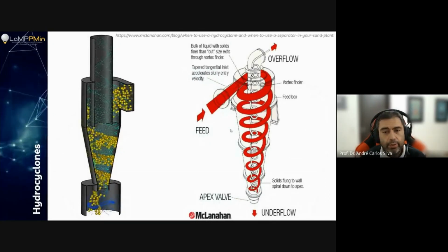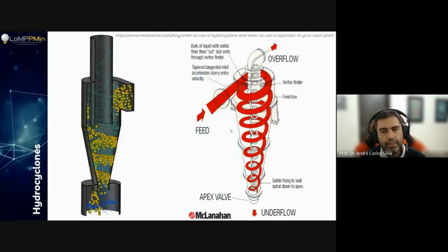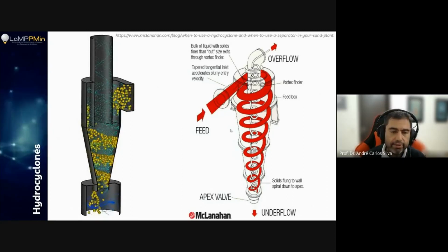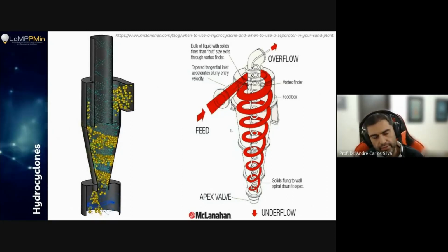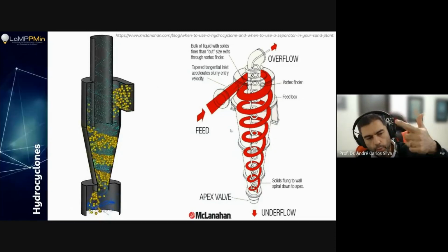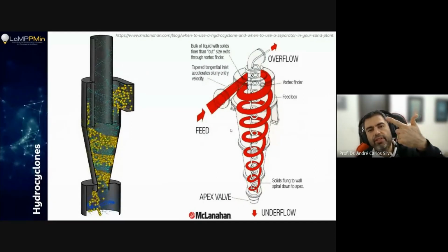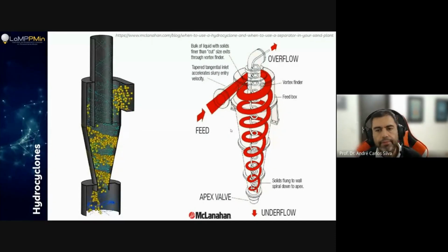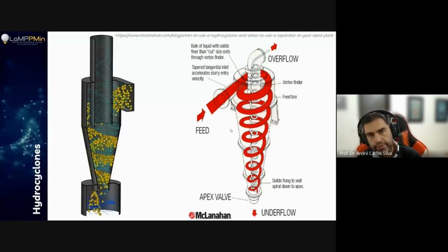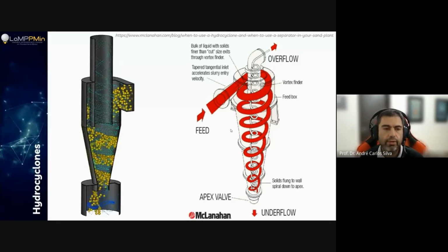Guys, to almost finish up our lecture today, I have to go to hydrocyclone. Okay, and in here we can have air cyclones and we can have water cyclones, and then we have these three different names. We have air cyclones, water cyclones, or call it hydrocyclones, and people who just say cyclone. Okay, let's consider something first. What does this machine do? One thing that you can say for sure is it's going to separate material according to size.